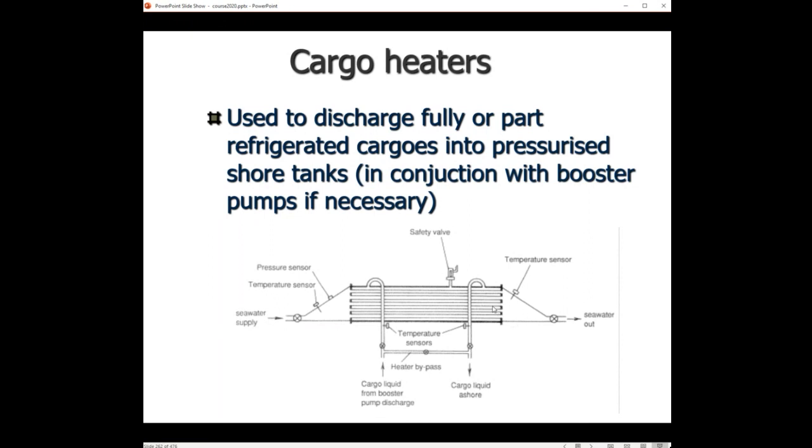And when the seawater starts freezing around the tubes, these tubes will be broken, heater broken, and yes, your holidays will start a bit earlier than expected. It's a very expensive equipment, as you might imagine. So this sensor here, which registers the outlet temperature of the seawater, is a very important one and should not become below +5 degrees.